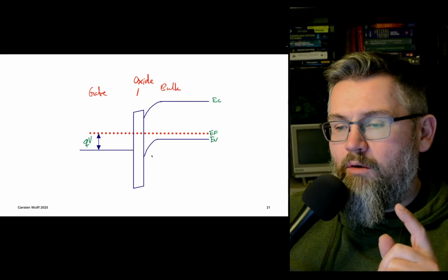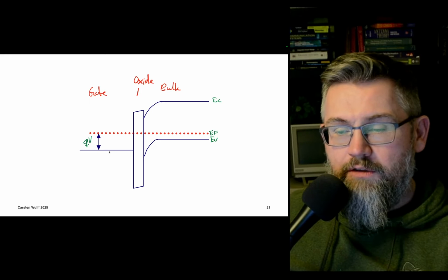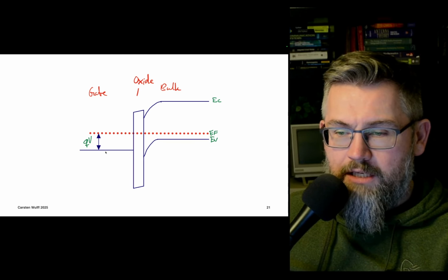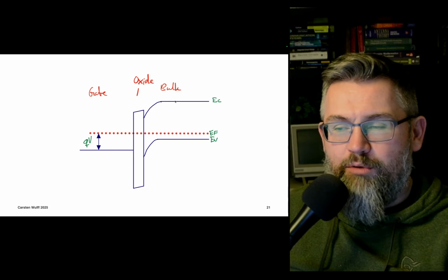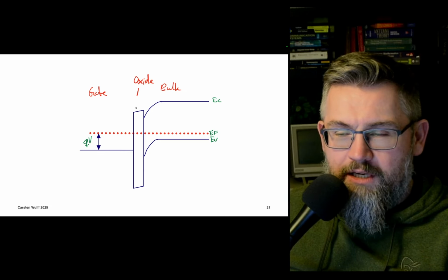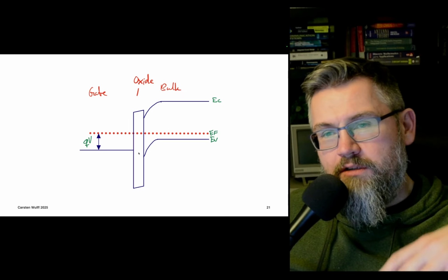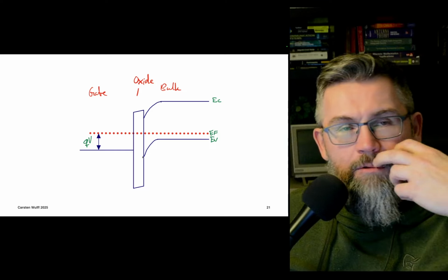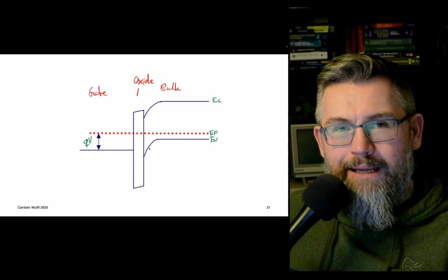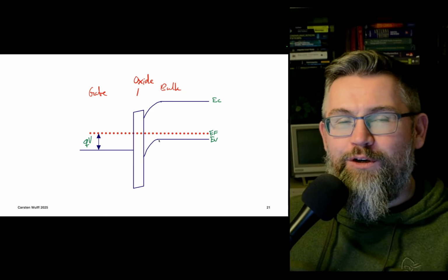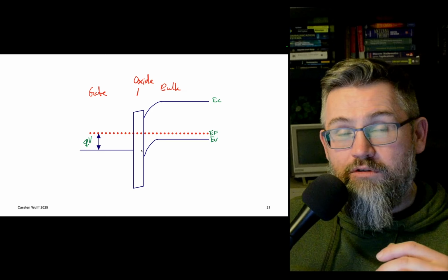Okay, now increase the voltage on the gate, and increasing the voltage is reducing the energy. So in this case, we pull the energy down. Now, this change in voltage has to disappear at some point. We're pulling the oxide down. We'll lose some voltage across the oxide, but not that much. But what actually happens is we're pulling the surface of the silicon in voltage, or in energy. It's more an energy barrier type of thing. So we're modulating the bending of the bands. Both the conduction band and the valence band will bend in energy closer to the surface of the silicon.